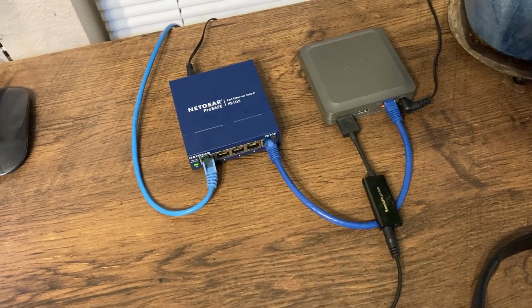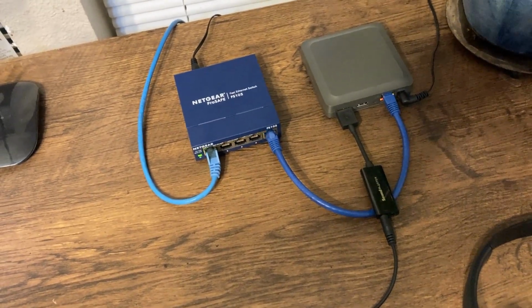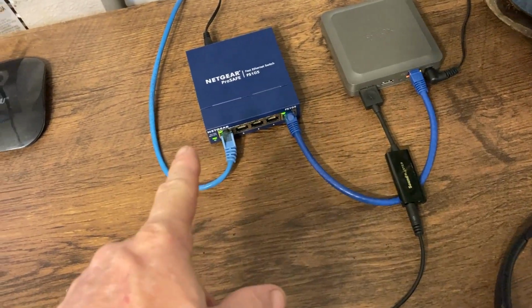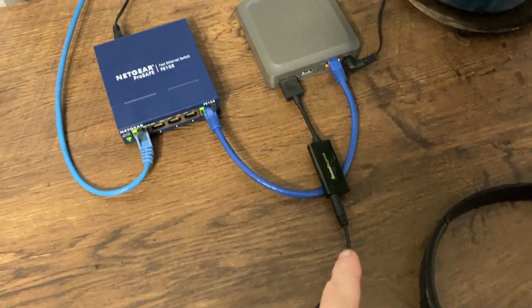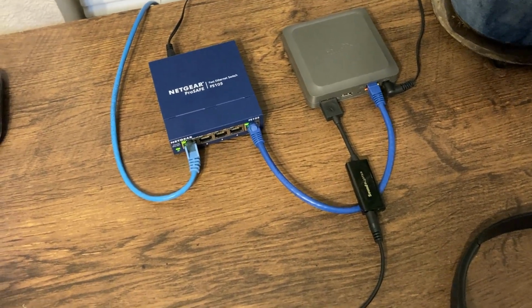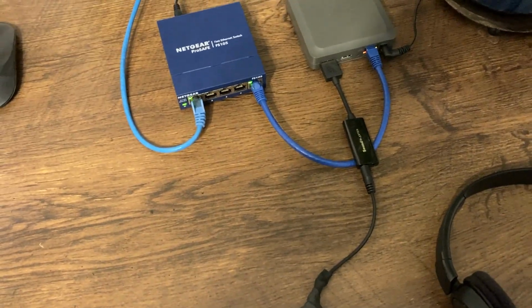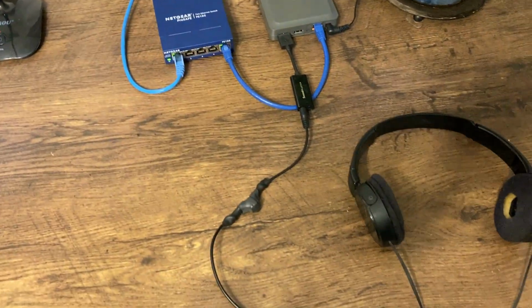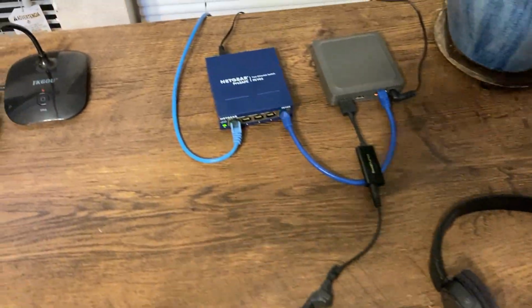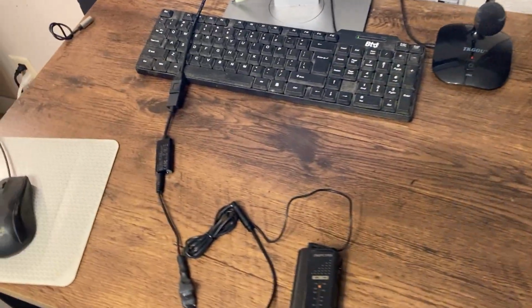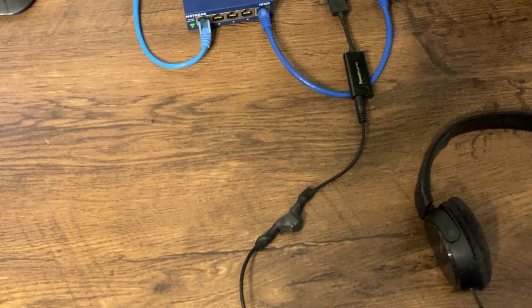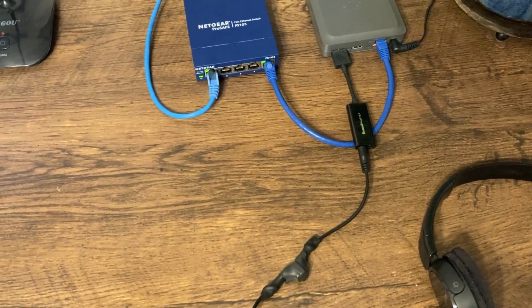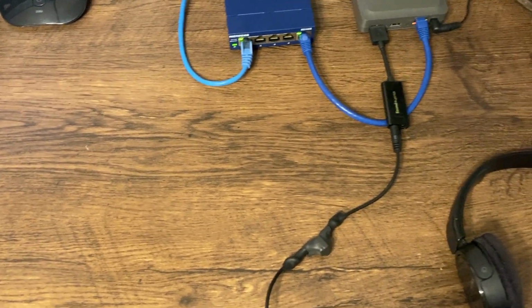that's on a USB server, and that USB server is connected through a network connection back to the PC. So this sound card is attached to the PC like it's plugged directly in, and we're just sending sound from the output of that sound card into the headphones. So that's the setup, it's really simple, and as you can see, I'm using 600 ohm 1-to-1 isolation transformers just to get the levels right and quiet the buzz.